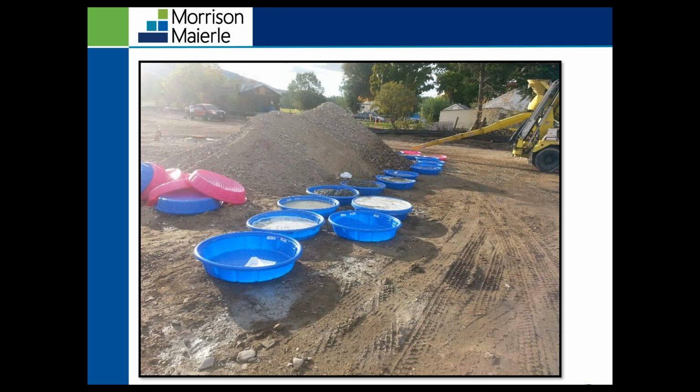There's multiple options to use. Like I said, this one's just a kiddie pool. You can dig a hole, line it. You have above ground construction concrete washouts where you're making sure you've lined it. There's a lot of commercial products that you can use. So just making sure you have a way of using a concrete washout, make it easily accessible for the concrete truck drivers. Place them where concrete's being poured. Just makes it more likely to be used.